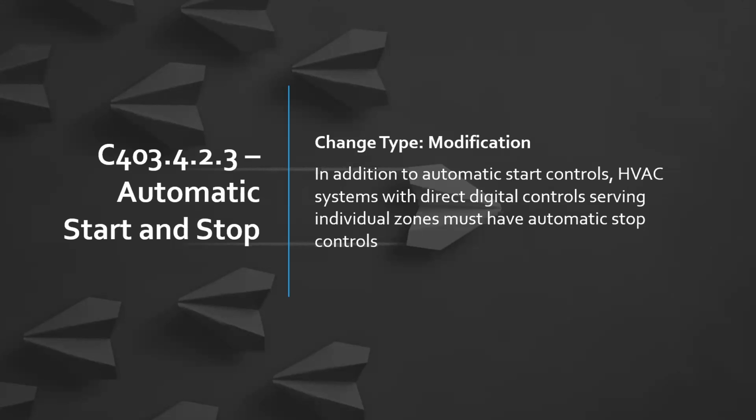And then also automatic controls shall be configured to automatically adjust the daily start times. So if it's supposed to come on at 7 and it's 5:45 and the temperature is still increasing but it's too high, it now knows whether or not it's going to get to that point when the system kicks in when someone occupies the building, so it can start prematurely to occupancy.